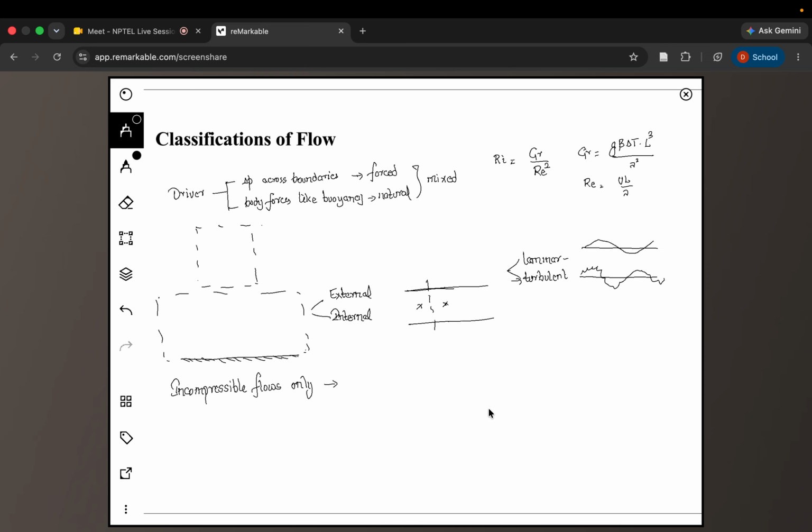But for now, the idea is laminar flow is a simple flow where you do not have any scales. Again, scale is a word that I have not introduced before. But the idea in laminar flow is you have a layer-like flow, so you have the streamline and streakline concepts that we discussed before. Once we move on to turbulent, then we'll be having these small disturbances that have to be accounted for, and they increase the heat transfer in certain scenarios, and they also decrease the heat transfer in certain scenarios, depending on where they occur. And so we need to have a basic understanding of when they increase the heat transfer, and if you have a particular application where you need to increase the heat transfer, how to introduce this turbulence into the flow so that your heat transfer will be increased.